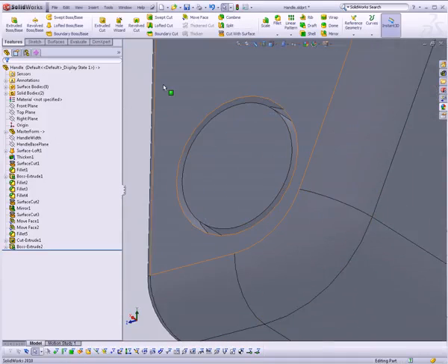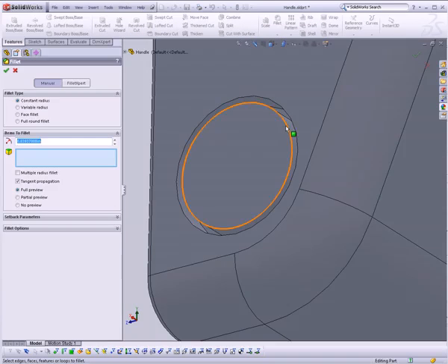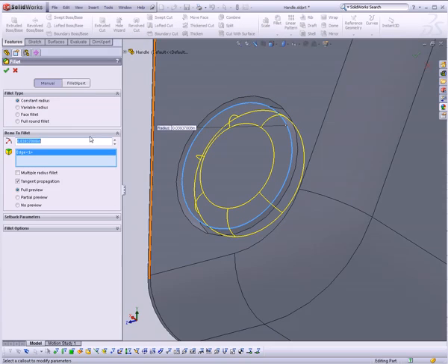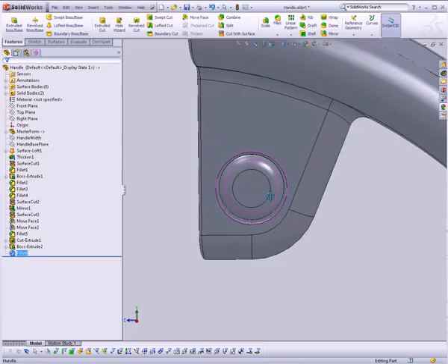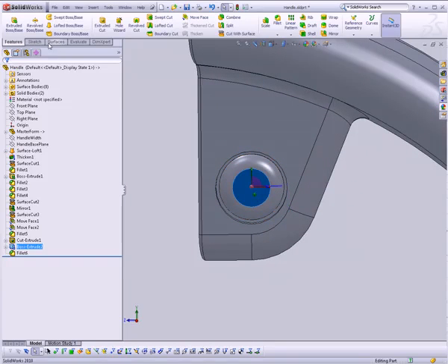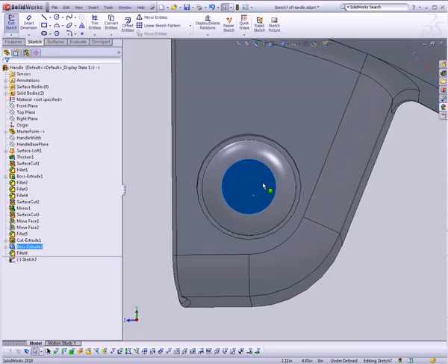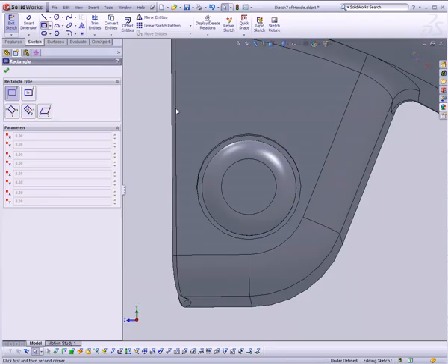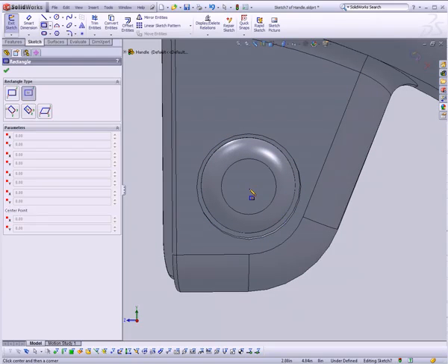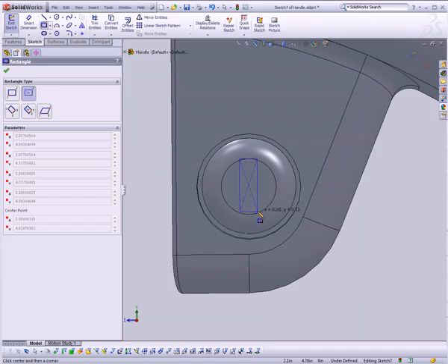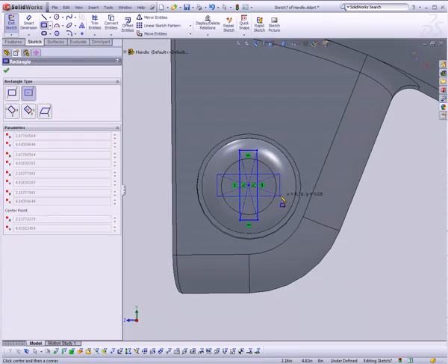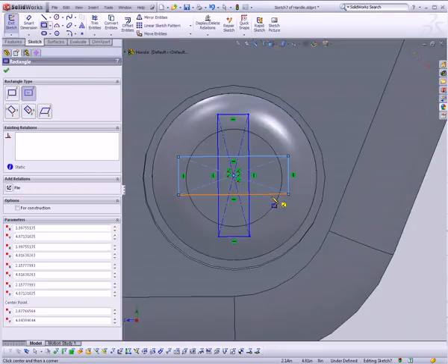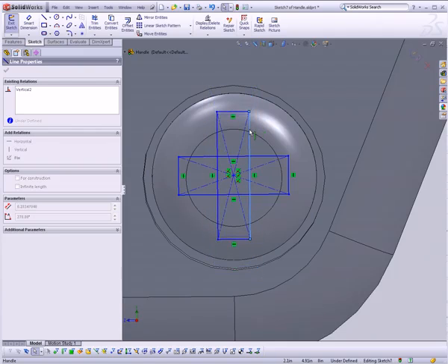Just put a great big old fillet on this edge. Maybe 0.05 it looks like would work. Yeah. And we can add an extruded cut to make the actual Phillips head holes. I'm going to do rectangles from center, just right here in the middle. And again, since this is not a mechanical part, this is a visual part only, I don't even need to dimension this.